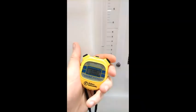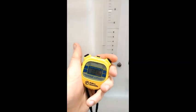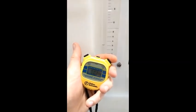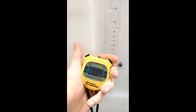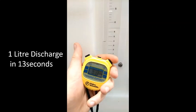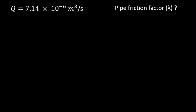The first thing we need to know is the flow going into the pipe rig, as the incurred head loss will depend on that. We measured the flow by simply recording the time it took to discharge 1 liter of water. In this case, it took 13 seconds for 1 liter of discharge to occur, which gives us this flow rate.